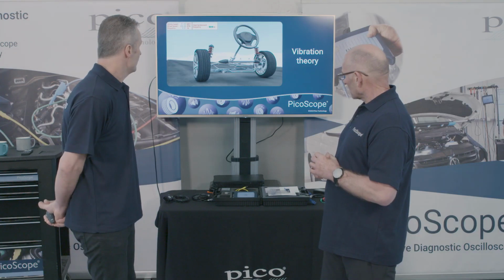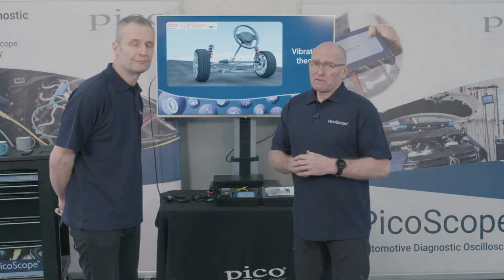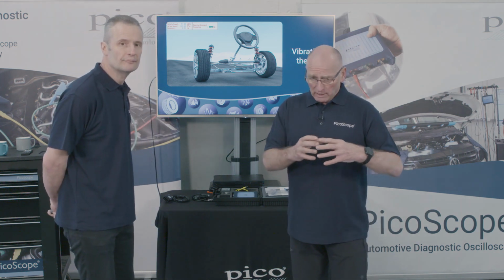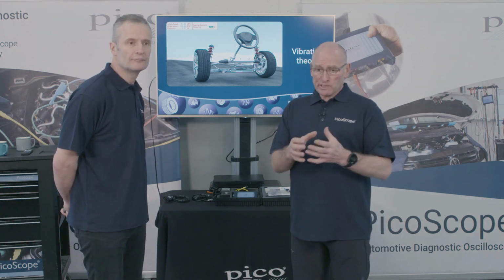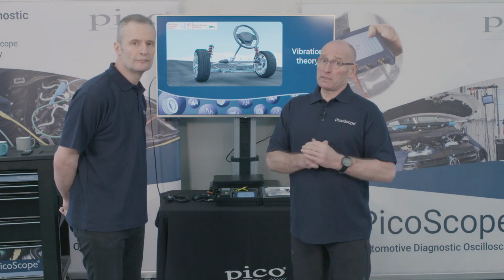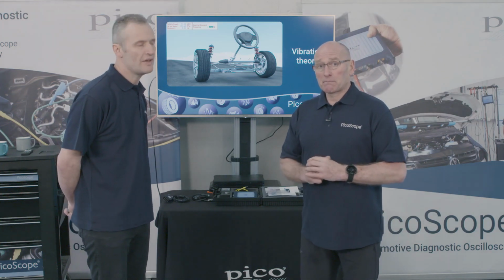And generally in this scenario, we rectify the source of our vibration. I think the big issue here as a technician, from my point of view, is that in order to understand the source, we're actually preventing premature failure of components, because this energy has to be absorbed by different components: bearings, suspension, shock absorbers. If there is an issue there, it's important we deal with the cause of the problem, therefore protecting the life of a component from premature failure. Yeah, consequential damage.